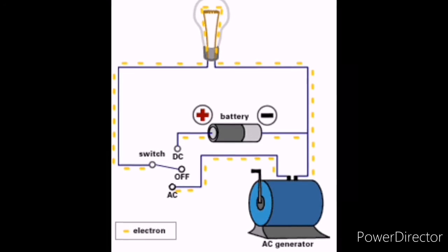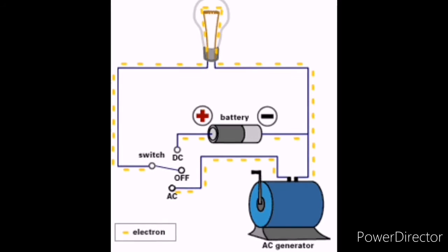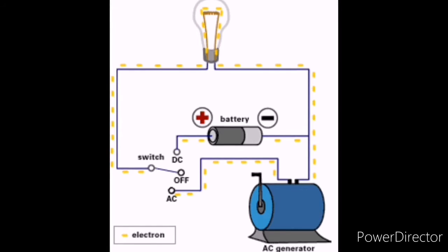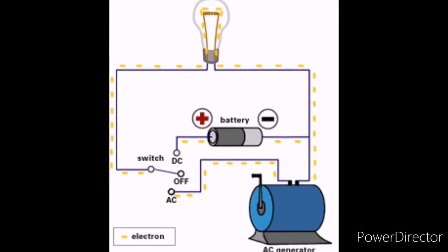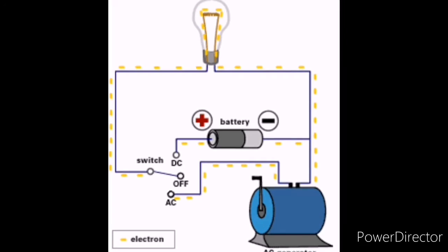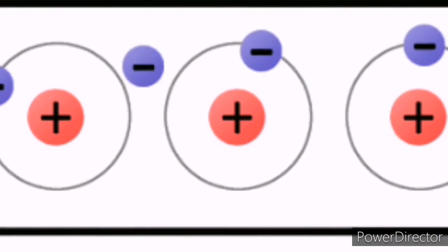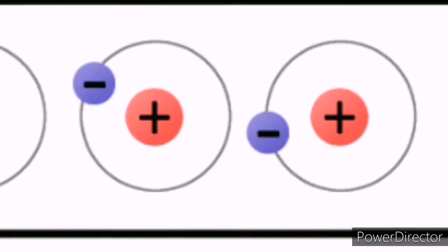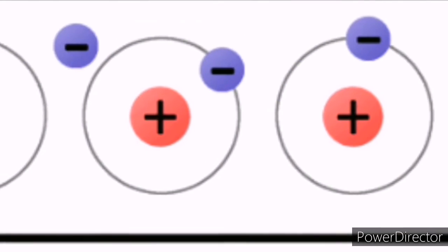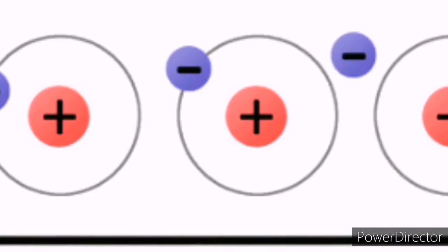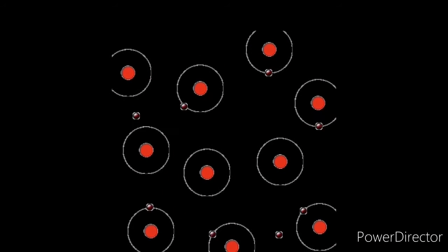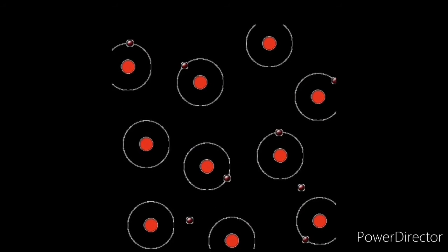Instead, the charged particle simply needs to nudge its neighbor a finite amount, which will nudge its neighbor, and so on, until a particle is nudged into the consumer, thus powering the machine. Essentially, what is occurring is a long chain of momentum transfer between mobile charge carriers. The Drude model of conduction describes this process more rigorously.